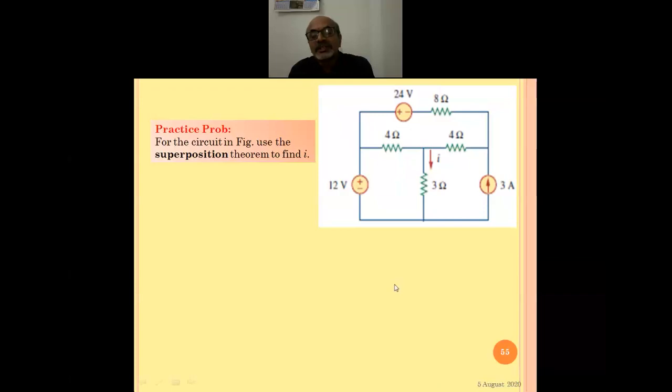So here dependent source has no responsibility as such for the contribution of this because it depends on the internal factor. So it is not separately supplying the current for this. In fact, the value of this depends on this current. When there is no current here, so there is no source here. It is not like that. So 20 volt will be always there, even though there is a circuit connected to this or not, 20 volt, that is the EMF of this source, will be always there.